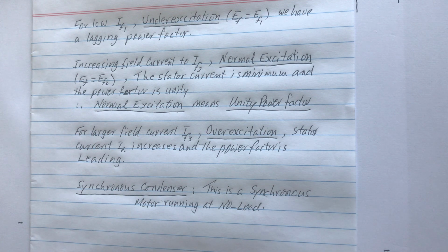For example, you have a transmission line coming from generators in Aqaba to Amman, the industrial area in Sahab. There, by the time you reach Amman, we will have a voltage drop, and there are big synchronous condensers in the substation in Sahab. What they do is try to bring the terminal voltage of the transmission line back to its original value.